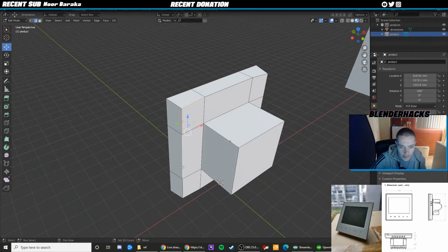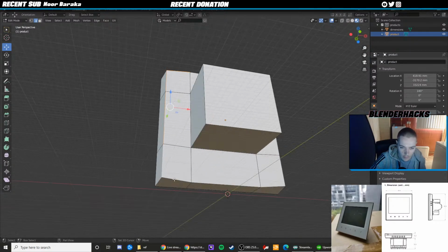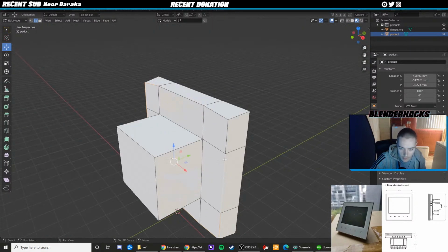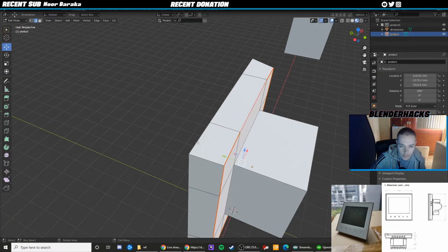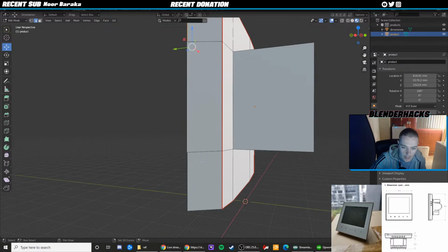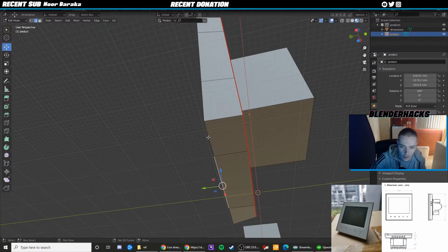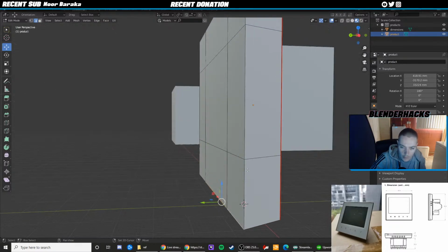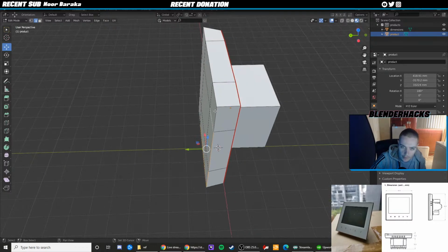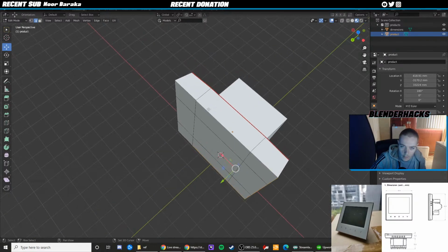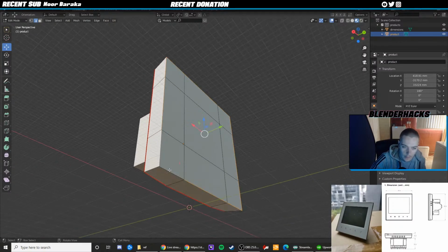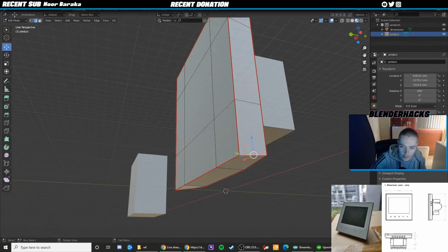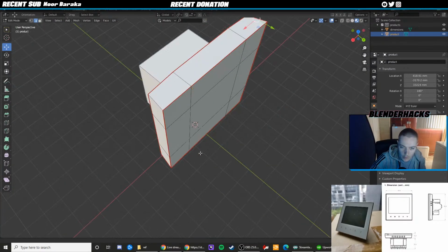Now, before I complicate the model too much, this is a very good piece of advice that I've learned doing modeling like this, is that you want to actually add your UV seams if you're going to be adding labels or materials, textures to your model, before you overcomplicate the model with vertices, edges and geometry. If you leave it for afterwards, you'll find yourself creating this really nice detailed model with good topology and everything, I hope.